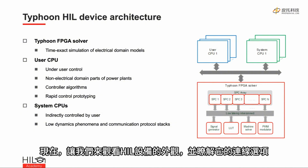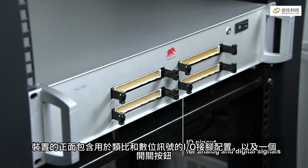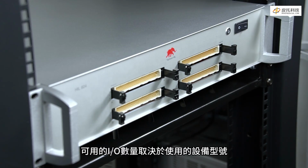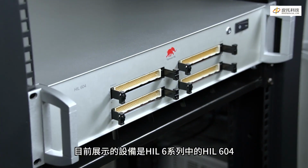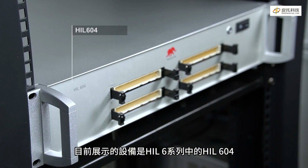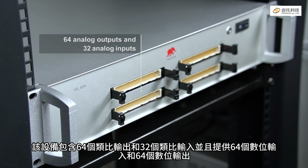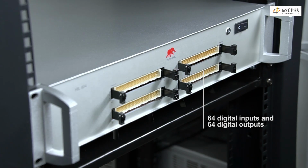Right now, let's have a look at the HIL device from the outside and learn about its connectivity options. The front side of the device contains an I/O pinout for analog and digital signals as well as an on-off button. The number of I/Os available depends on the device that you are using. The device that we are demonstrating today is from the HIL 6 series, HIL 604. This device contains 64 analog outputs and 32 analog inputs. It also has 64 digital inputs and 64 digital outputs available.